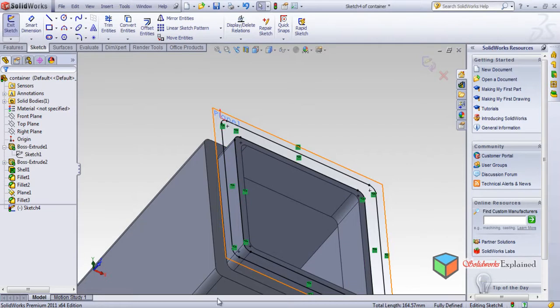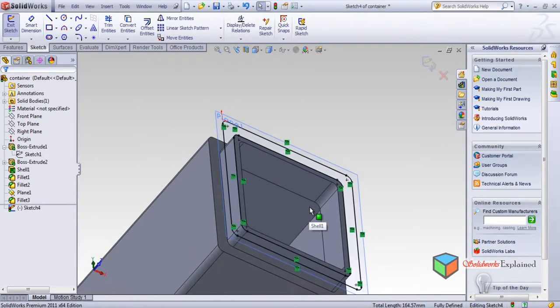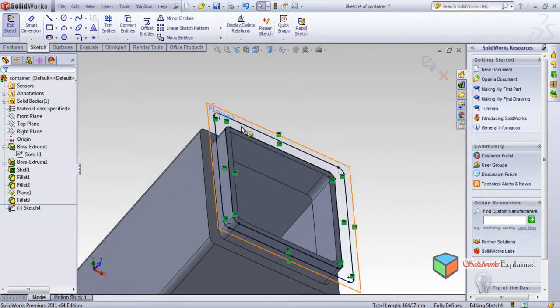Now once this black line is made, I could also make this black line on a plane using my sketches. Like I would make the rectangles and then fillet it, and then use the dimensions which were used to make this bottle. But rather than doing these things, this is a very easy way to convert entities on the plane.